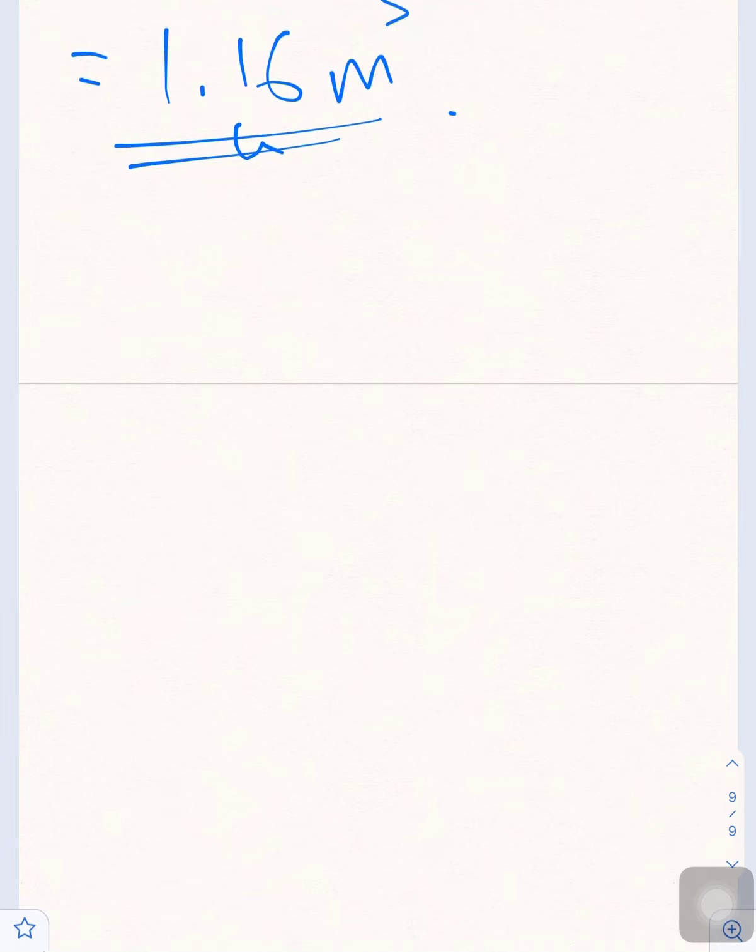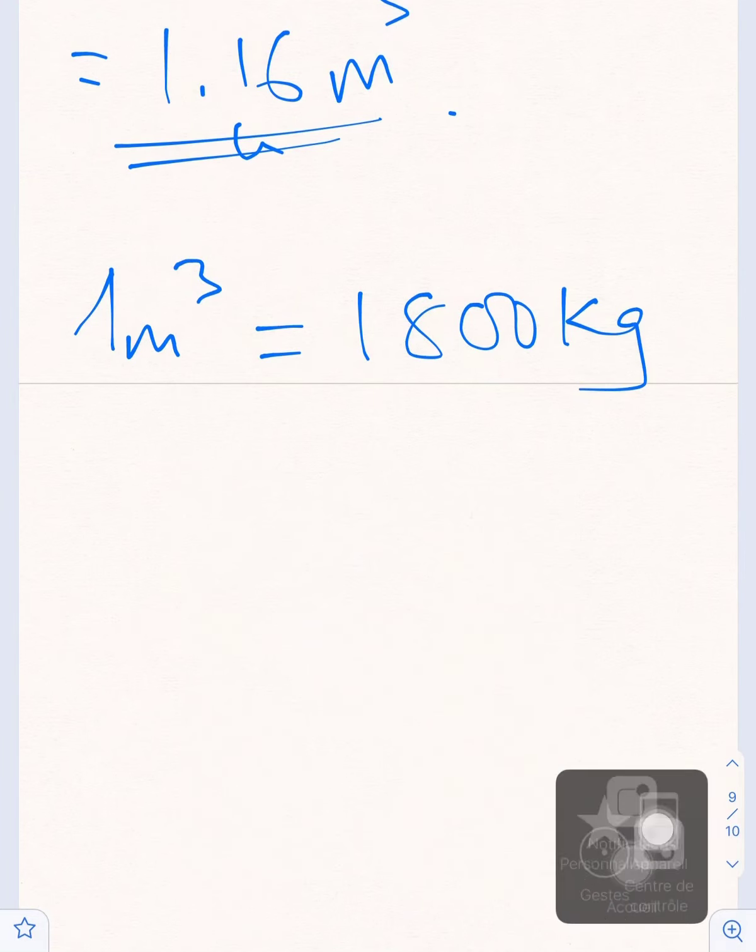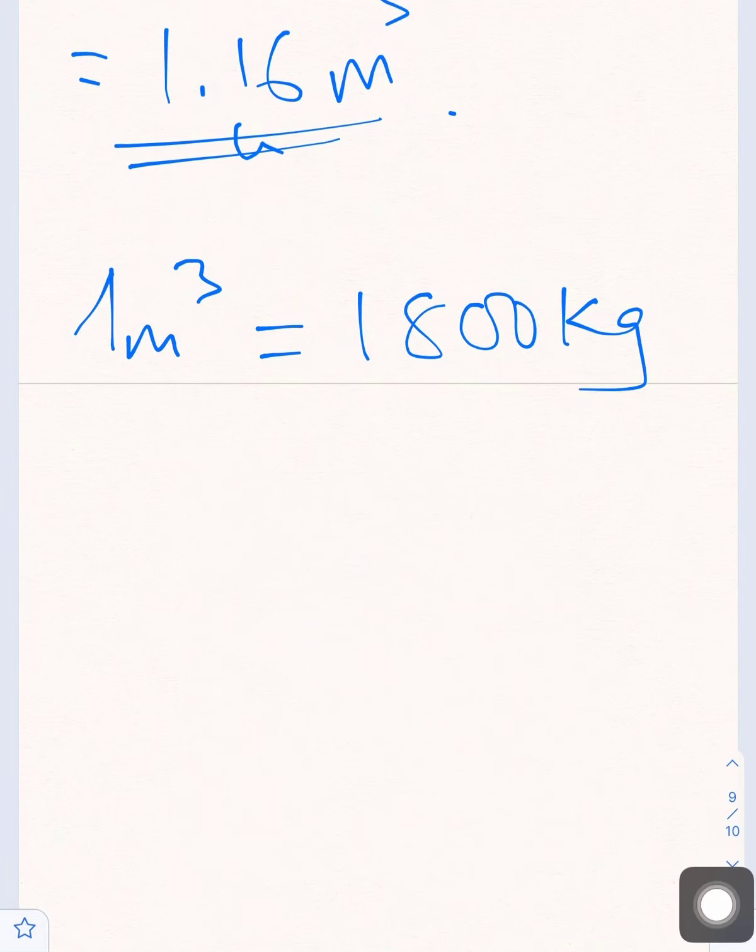When we reach here, we apply the same method that we applied, in anticipation that 1 cubic meter of coarse aggregate, because we studied as engineers, is about 1800 kgs. So these are ratios that should be at the back of our minds as engineers.